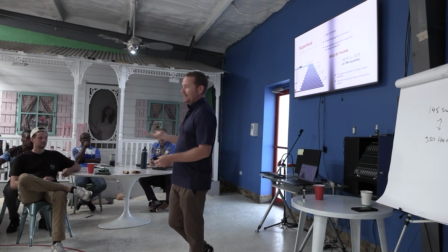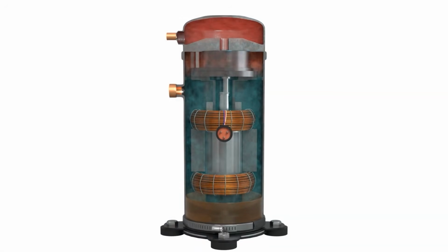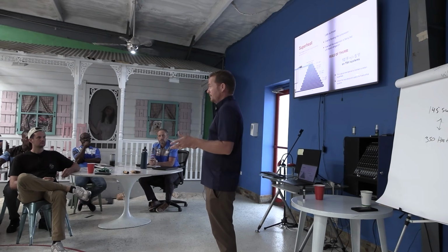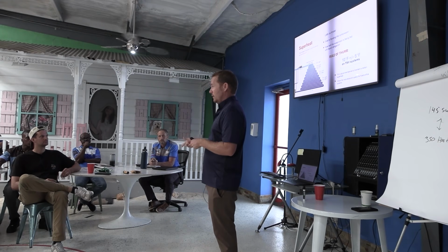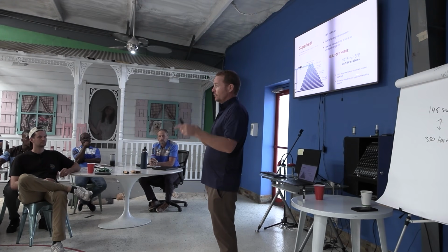No, it's not, right? Because it's got this cool vapor going into it. That's what's supposed to keep the compressor cool, not the air around the compressor. So it's a refrigerant-cooled compressor. If that refrigerant isn't cool because the suction line isn't properly insulated or it's way too long or whatever the case may be, that's a problem. So we do care what the superheat is outside, but for a different reason.